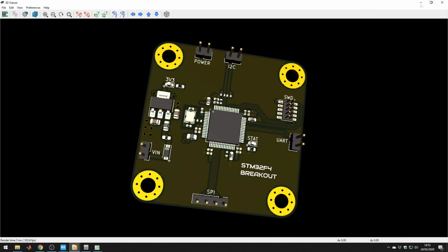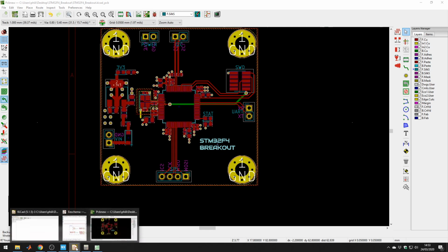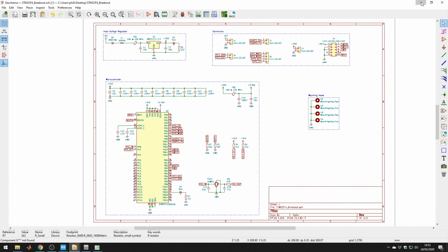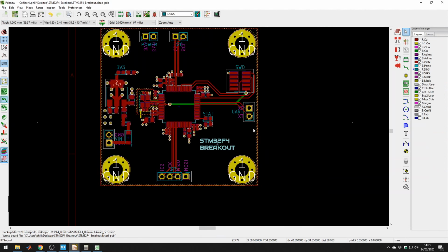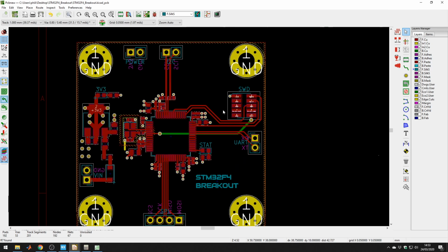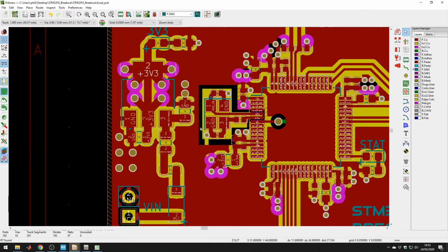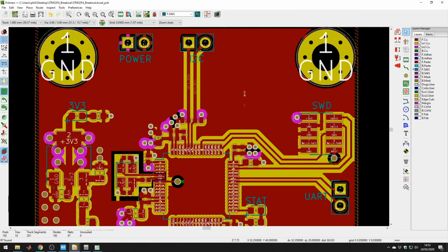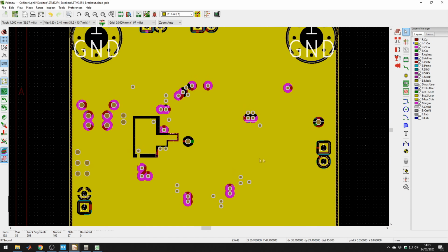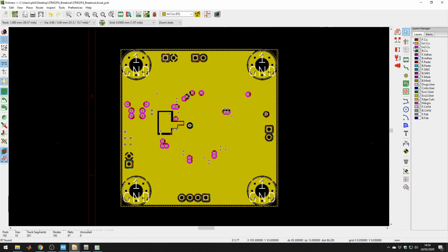Okay, so right now it would be a very good idea to just check the whole routing again. Again, check the schematic, make sure everything's correct. Check the data sheets, cross-reference. Of course, for a large project, this is vitally important. So it makes sense to just try it for smaller ones. Just go through the routing, make sure that the traces look good, all the copper fills look good. Like that. That looks alright. Make sure there's enough clearance, so the copper fills aren't chopped up too much.